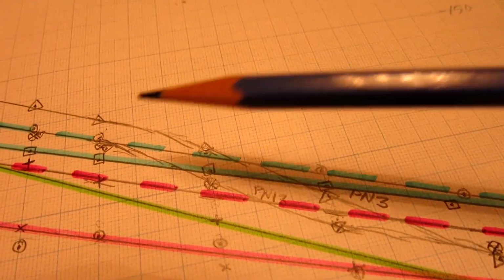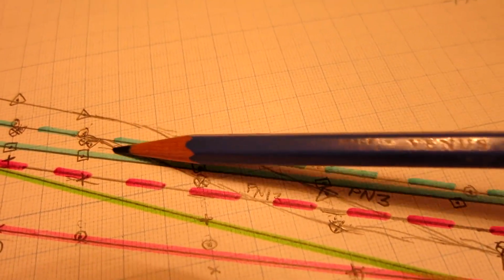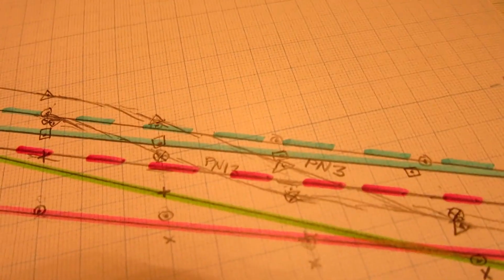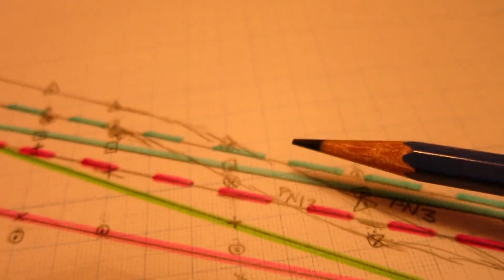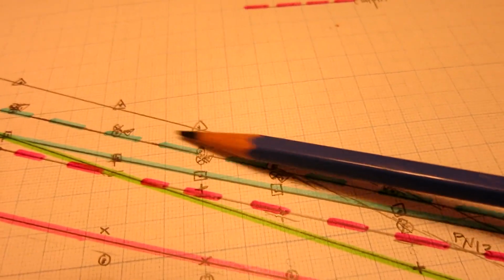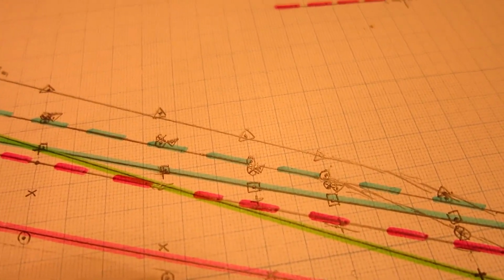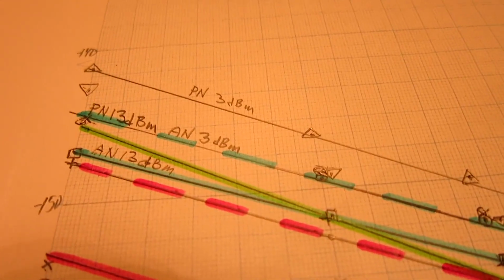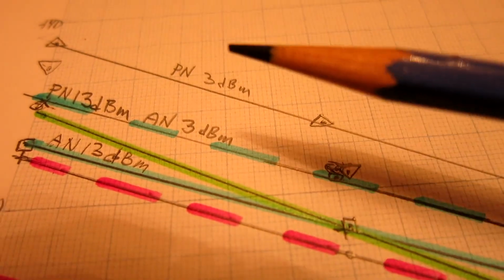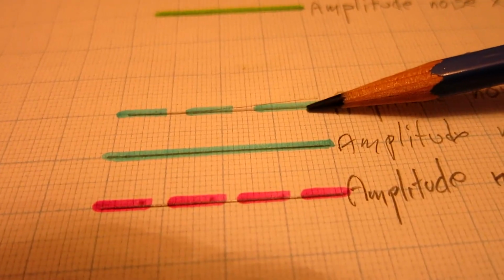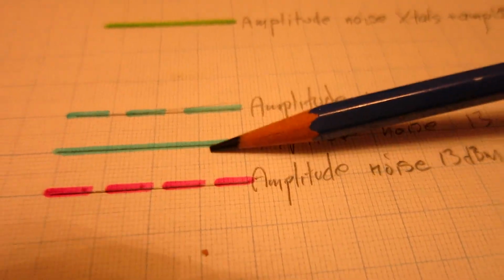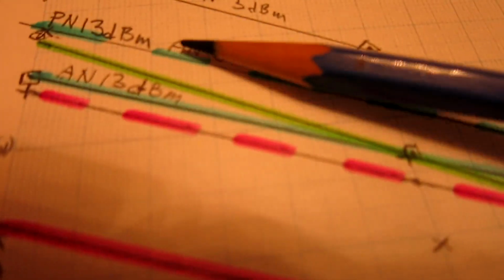The phase noise at 13 dBm has the same behavior. It goes down at this, which is 100 Hertz, from the expected extrapolation of the straight line. Maybe I will look at that later, but the interesting thing now is that increasing from 3 dBm, that is this dotted blue line, to 13 dBm, the solid blue line, it improves from here to here.